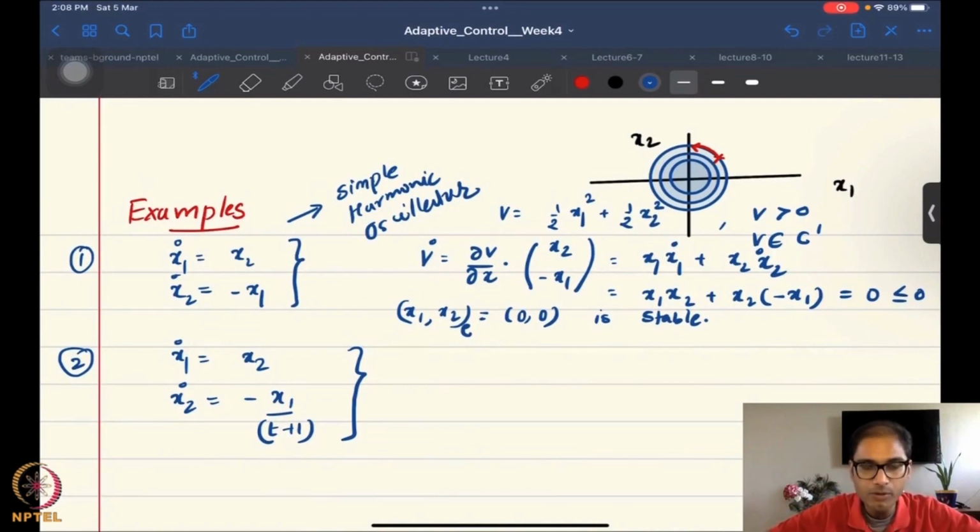We've already applied Lyapunov's theorem, and learned to some extent how to apply it. We start by choosing a V, and we have to make sure that it is C1 at least and positive definite. Only then it is a candidate Lyapunov function on which a Lyapunov theorem can be applied. Then I compute V dot.